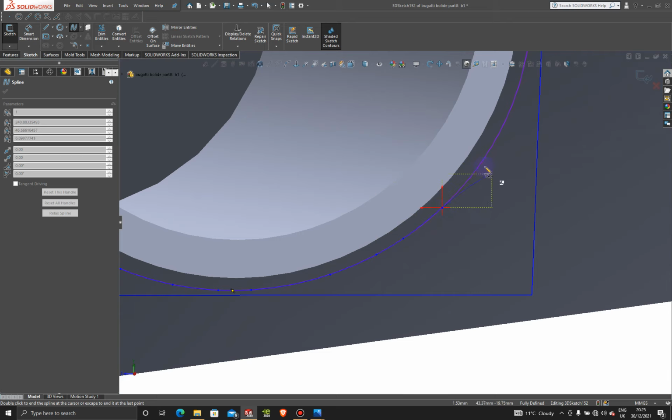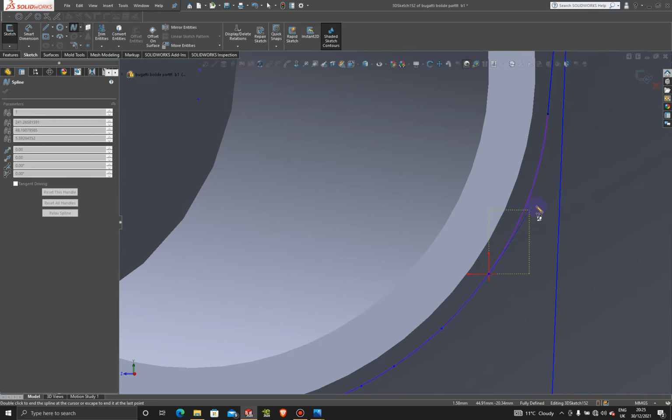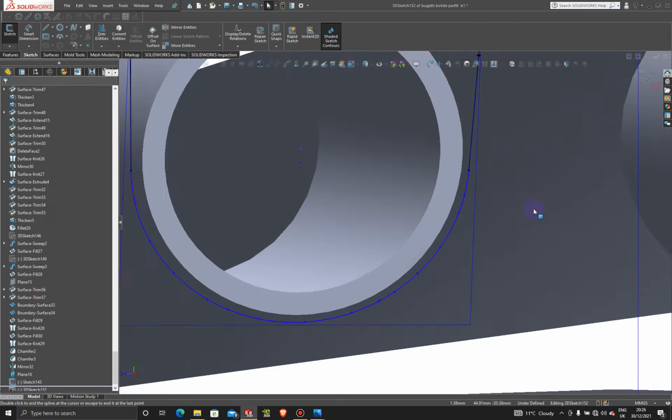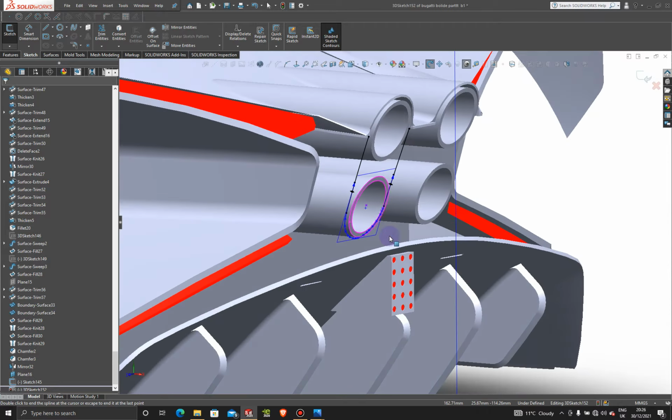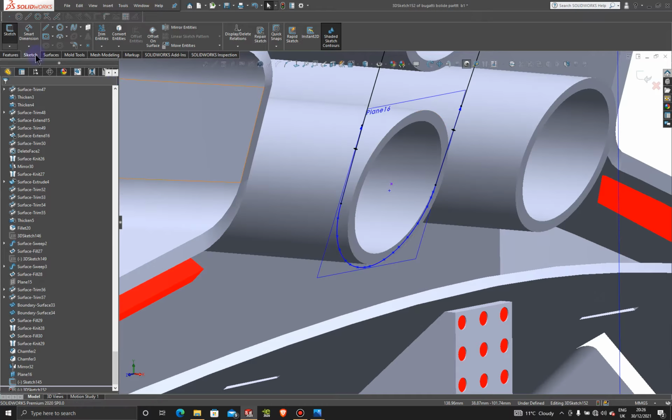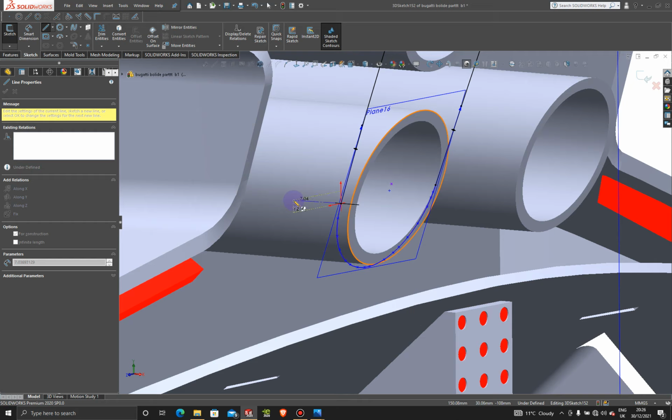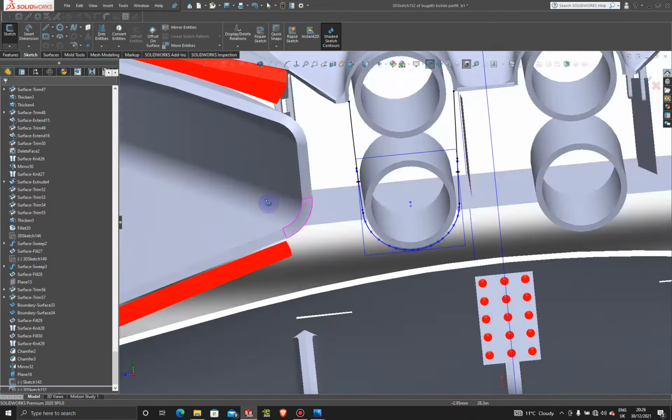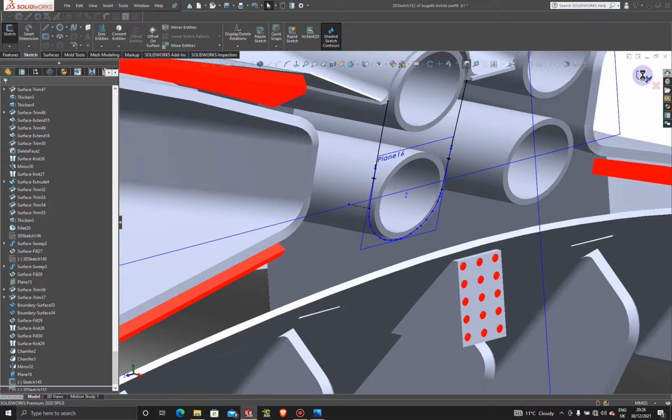And then just go around that line. And then we're going to connect to this point. All right, so once we have that, we're going to come to this side and grab a center line on this point, and we're going to press the Tab button to get into XYZ, to X and Y, and that's for direction. So that's going to be our direction of pull, of course, and then we're just going to exit the sketch.